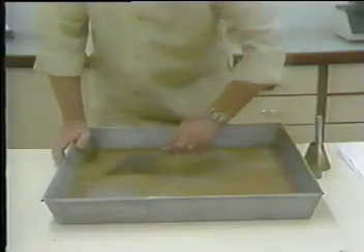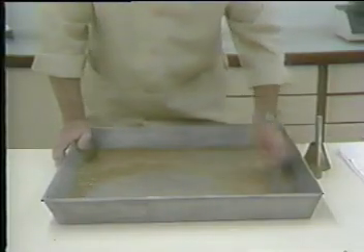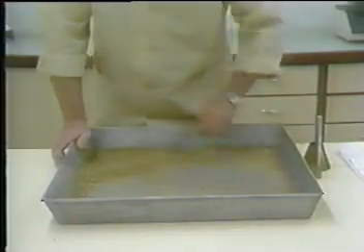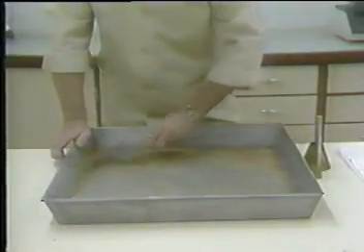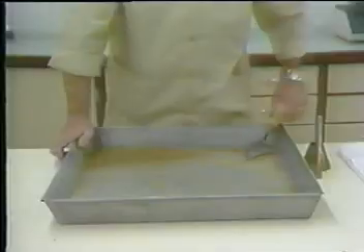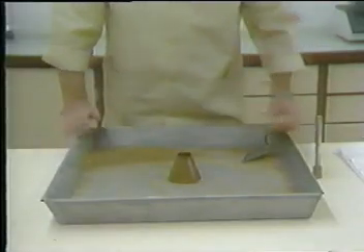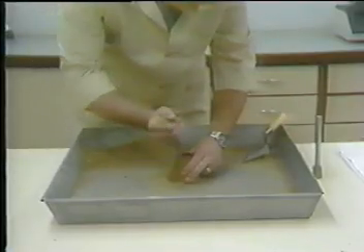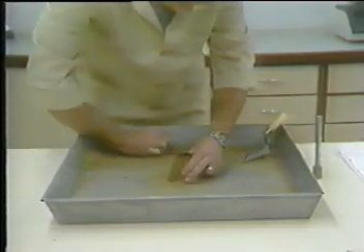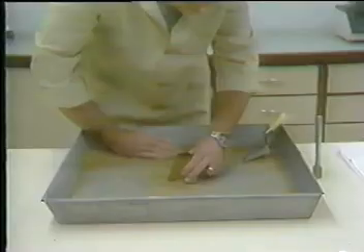Perform the cone test to determine when the fine aggregate has attained saturated surface dry condition. To run the cone test, use the mold previously shown and hold it firmly on a smooth, non-absorbent surface with the large diameter down. Place a portion of the partially dried fine aggregate loosely in the mold, filling it to overflowing.